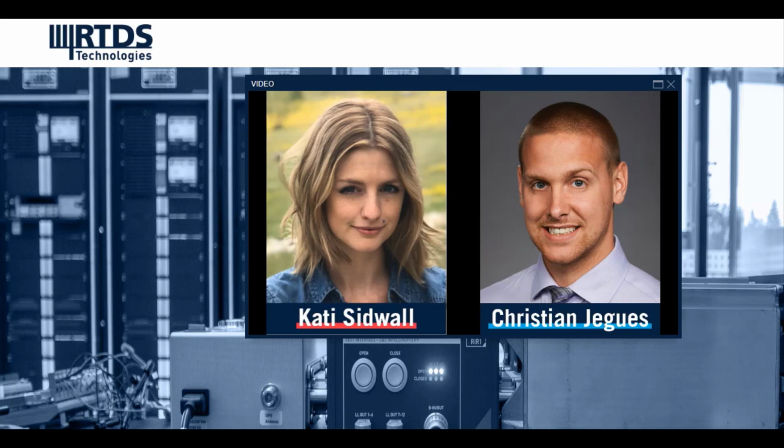I think if you want to do testing with multiple IntelliRupters, then what the IntelliRupters need to do is communicate with each other. So I think what that would also involve is connecting the communication modules of the IntelliRupters into the docking station. That information wasn't shown here, but it is possible to connect the communication modules into that docking station as I'd shown. And then you'd have to figure out how to get the various IntelliRupters to communicate with each other in order to perform this kind of testing.